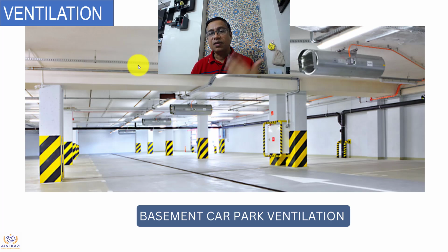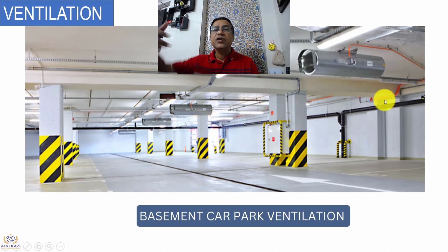But the modern technology uses jet fans, the displacement type jet fans, which can take the air from here, go to this fan, shift it to another fan, and then we have an exhaust fan somewhere over here which finally takes the CO out, right?